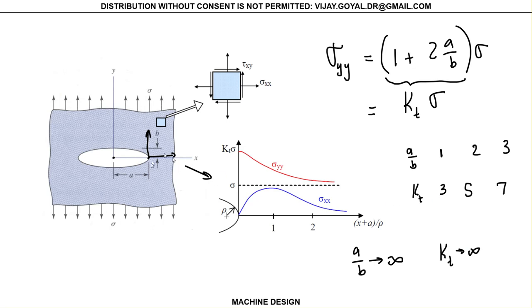I'm saying my stresses actually go to infinity, which is true because I'm working with a discontinuity. I really have a crack. I have a structure that is cracked. This is a singularity. Because there's a singularity, it's going to have infinite stresses. So in this particular case, as you can see, stresses are no longer useful.